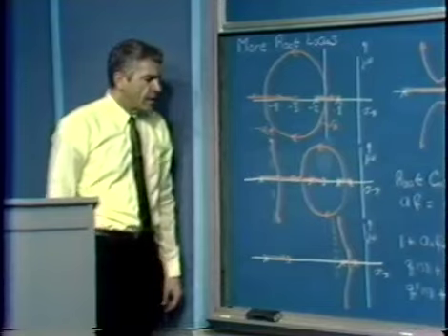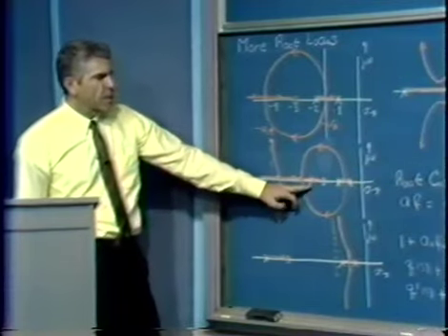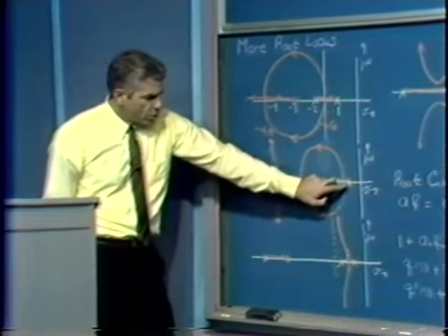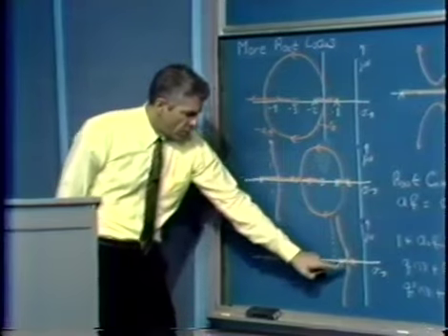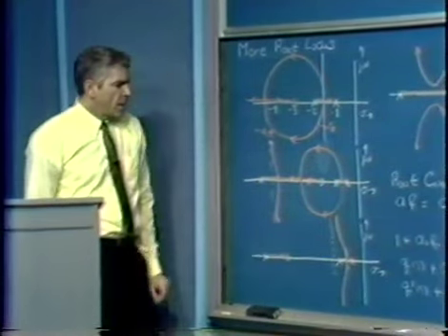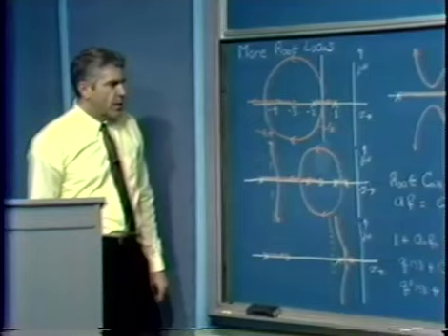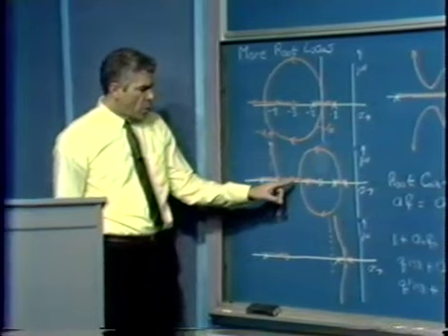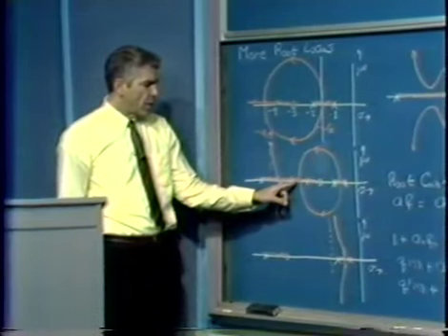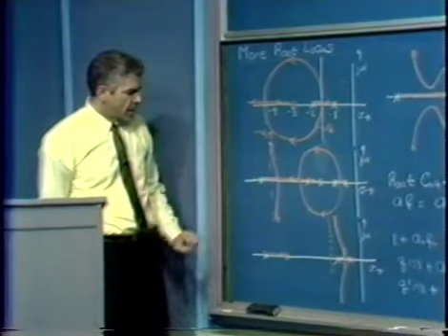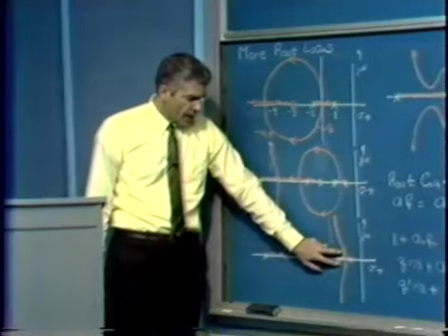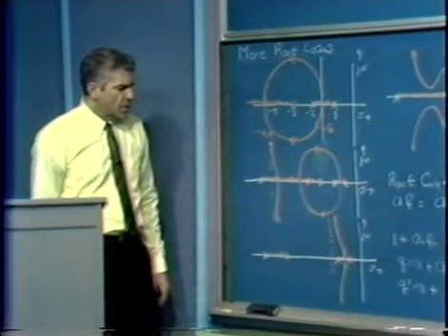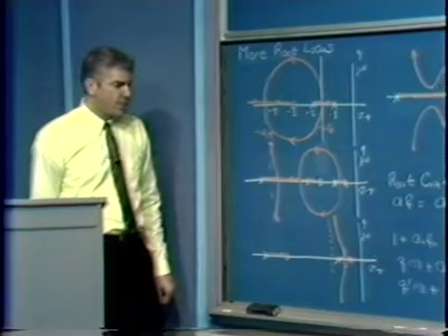It's interesting to look at the dividing line between these two apparently very different forms of behavior. We start out with two poles, a zero, and then a third pole in both cases. And yet we have root locus diagrams that look very dramatically different. One of them has the circular behavior, all of the branches lying for a while on the real axis. And in this case, we never have all of the branches lying on the real axis except for very small values of A naught, F naught. They look like very, very dissimilar kinds of pictures.